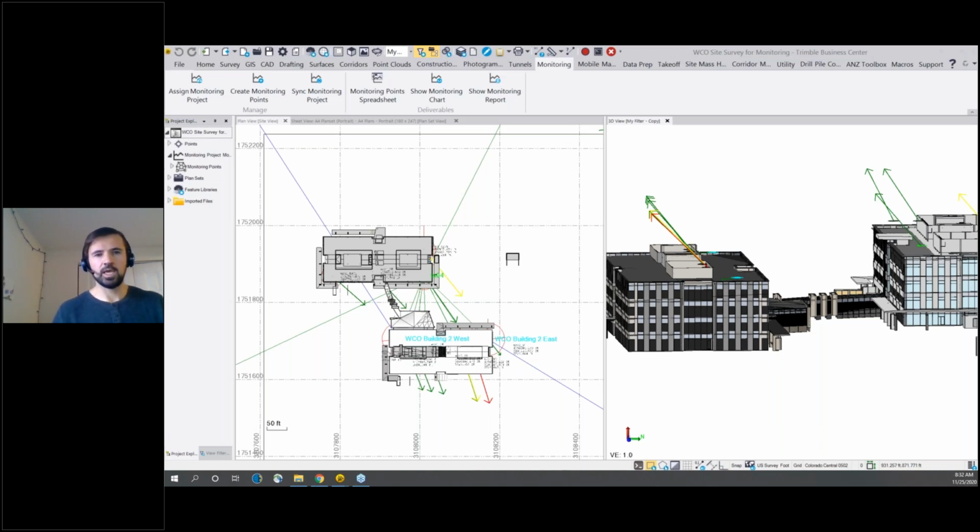So for instance, you know that your elevation is really tight because you're using a digital level. So you can set that threshold down smaller for that specific point, but you can set, let's say, maybe you expect the total station observations to be a bit more loose, and you can set the 2D threshold higher. So yes, you can kind of have different thresholds based on that. And as long as that point is defined by both the GNSS and the leveling measurement, then that will work.